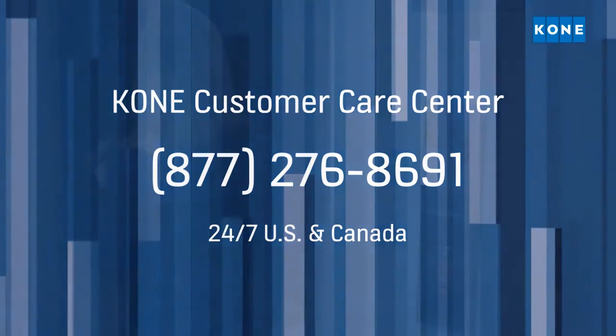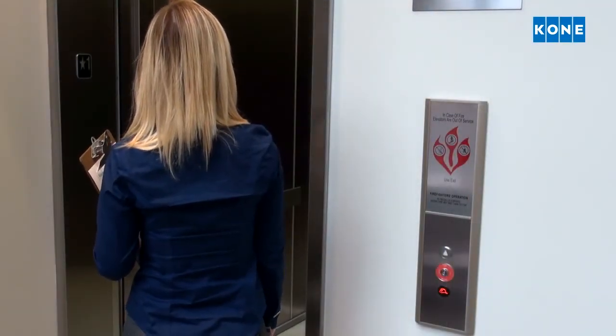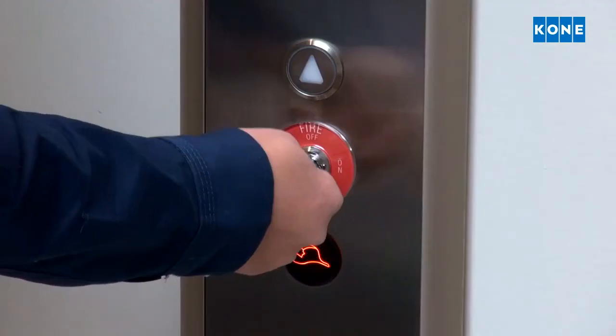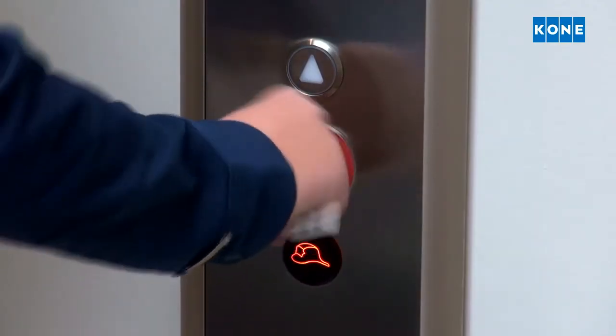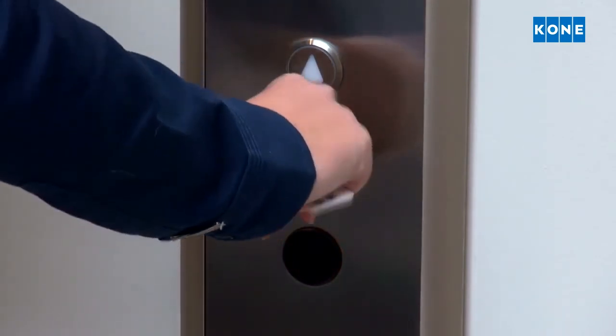To remove the elevator or elevators from Fire Service Phase 1 recall operation, turn the Fire Recall key switch, which is located at the designated egress floor, first to the reset position and then to the off position.